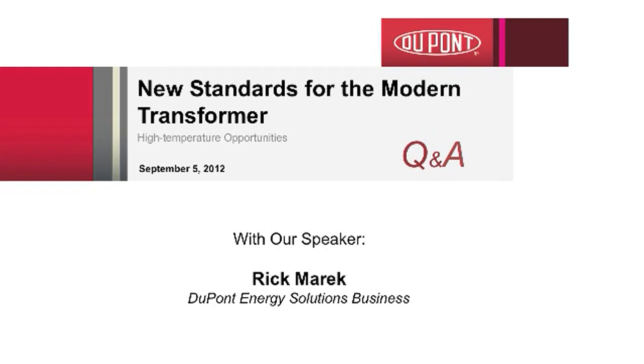Are you concerned, Rick, about the dielectric strength of the oil at the interface between the 150 degree C winding? Won't the oil create gas bubbles? Well, this will be a function of the gas saturated in the oil and also the moisture in the material. So a well-dried transformer that is maintained in a dried condition should not see bubbling conditions. Okay. Another question has come in.